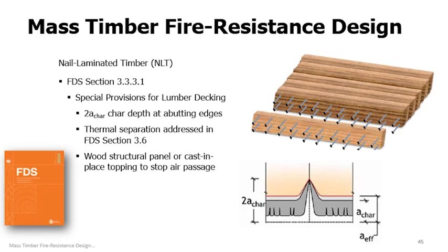This design method for timber decks has been validated using existing fire resistance test data, and it allows for optimized design of timber decks because it yields higher and often more accurate calculated fire resistance ratings than the NDS procedure, and that's especially the case for thicker timber decks.